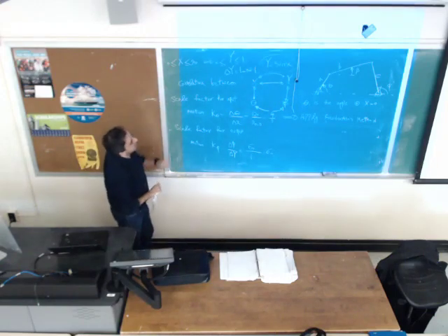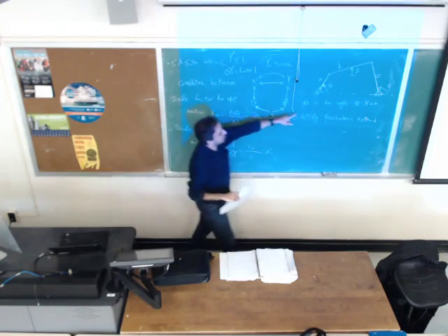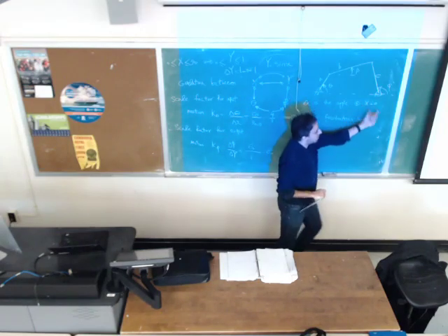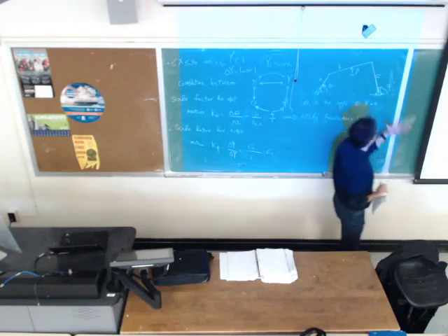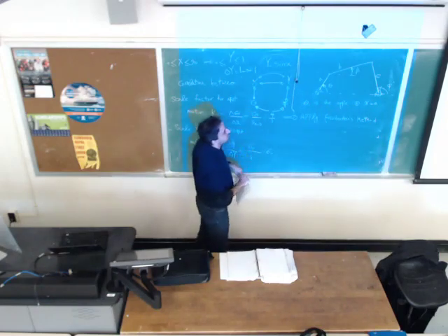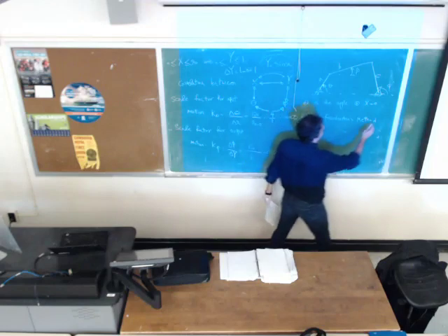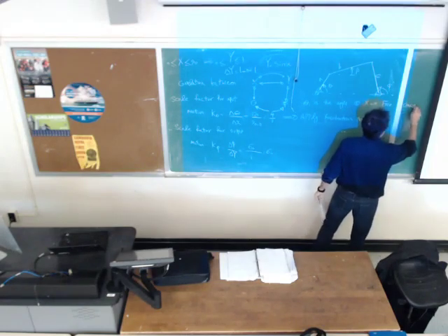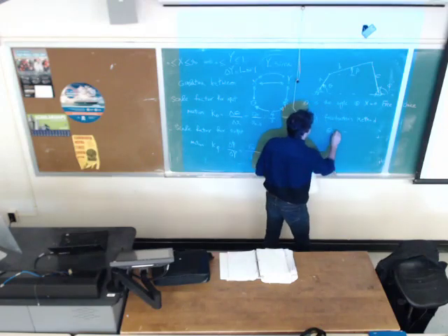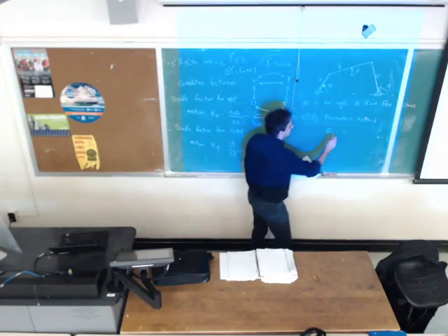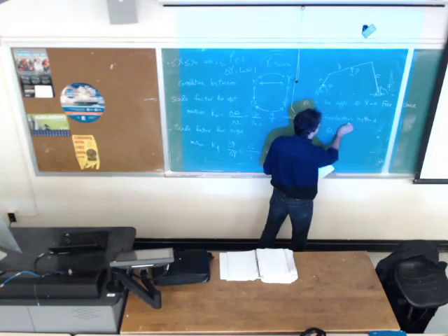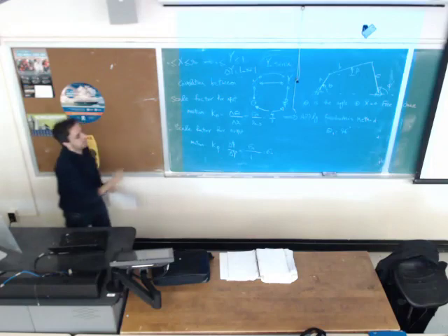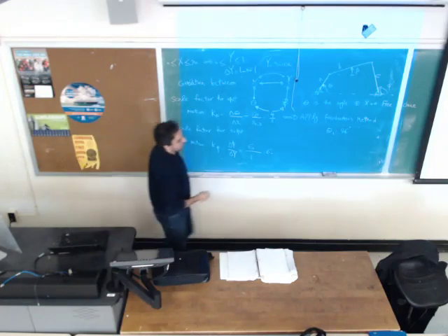The first point is 0. So what would be the angle of theta 1 when the input link is representing x 0? This is going to be the free choice. You pick the free choice. I pick 96 degrees. I just want to show you it shouldn't be necessary. It can be any number, depends on your interest.